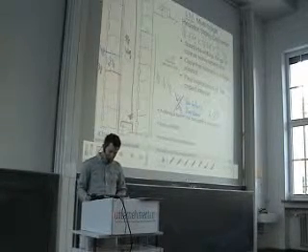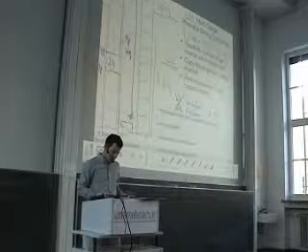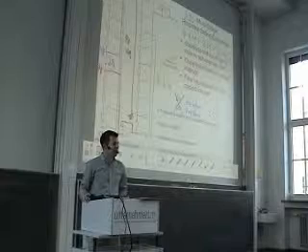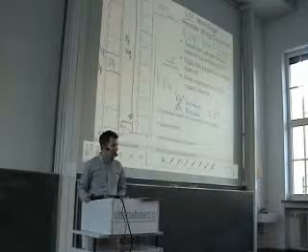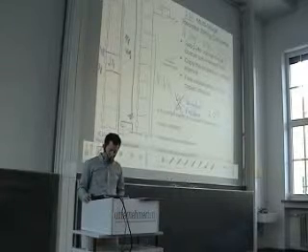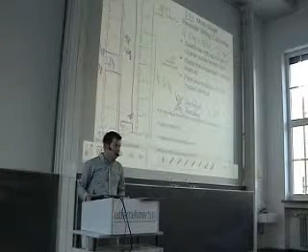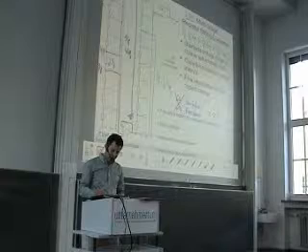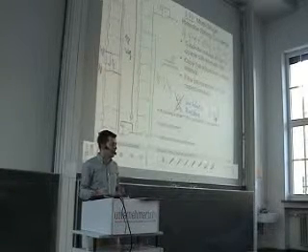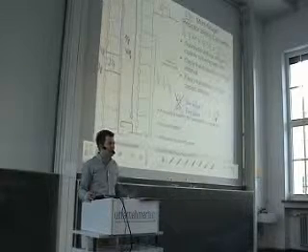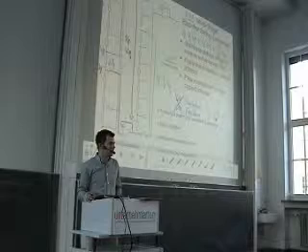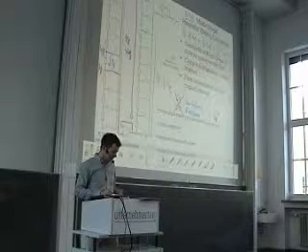This has been 3 or 4 architectures for resistor string based DACs. And you have seen as soon as we increase the number of bits, the effort explodes with this exponential. So here we have this 2 to the power of n over 2. In the other architectures we had even 2 to the power of n. Common to all of them is effort increases rapidly if the number of bits goes up.